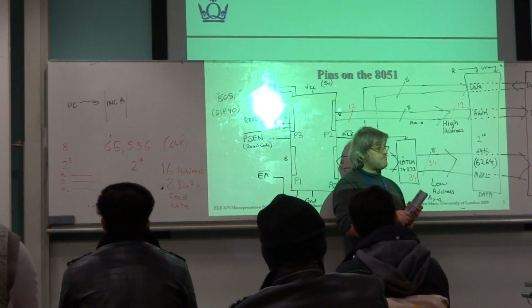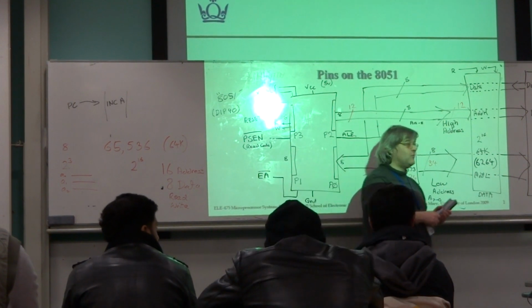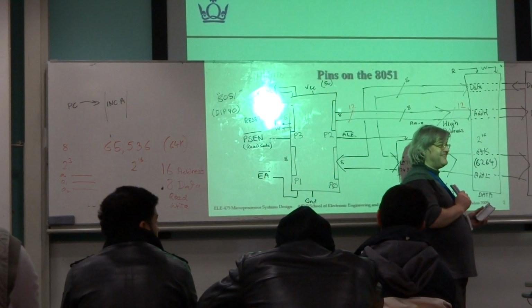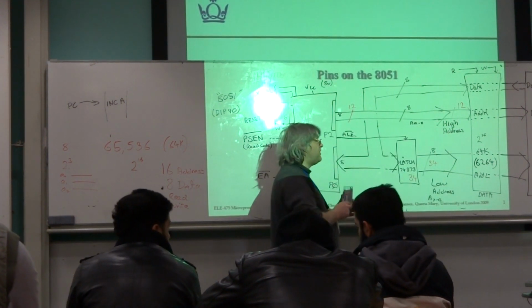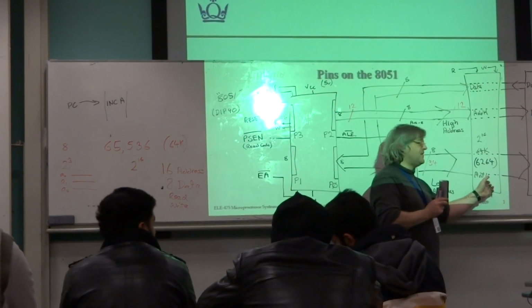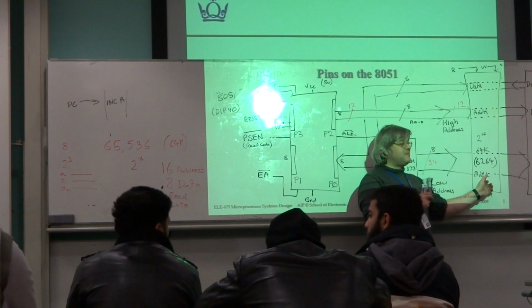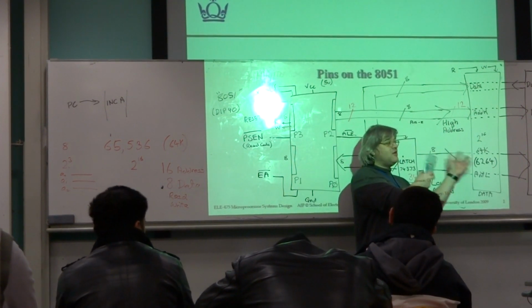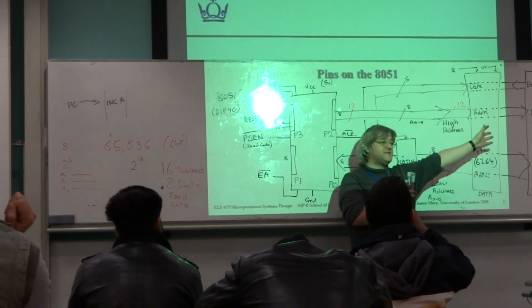Can you program it externally through the microcontroller? No, you can't, not without a bodge. There are ways around it, and I'm going to come on to those, but I probably won't do it today because it'll take me a few minutes to explain. But for now, assume that as far as the 8051 is concerned, no, you can't write to program memory. But there is a fix.